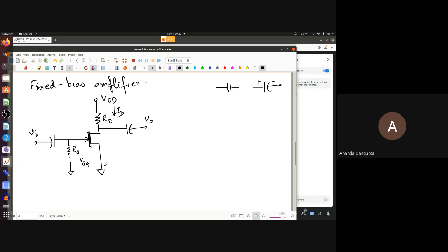That's our biasing analysis. The AC value is a fluctuation around that, and at least when we are dealing with a linearized version of this circuit, that is, a Taylor series with the first order only, then we are within our rights to use something called the superposition principle.